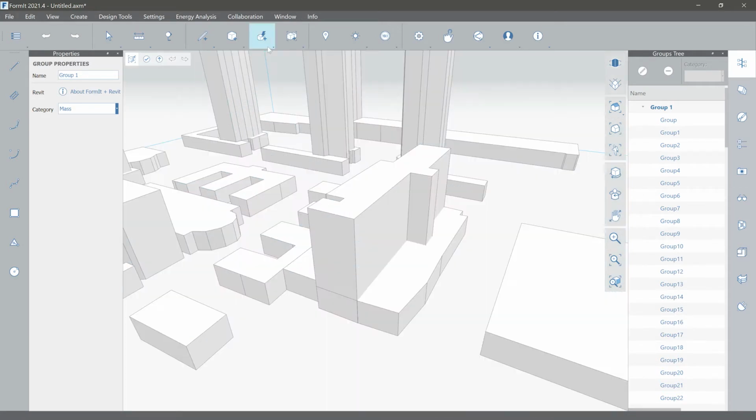I'm going to go to the advanced geometry tools and click on it and click join geometry, or the shortcut GJ, or actually JG, and click on the two pieces of geometry that I want to join. So that would be this one here and this one here. Once those two pieces are joined, I can click the select button or the check button up here, and it should nicely join both of those together.